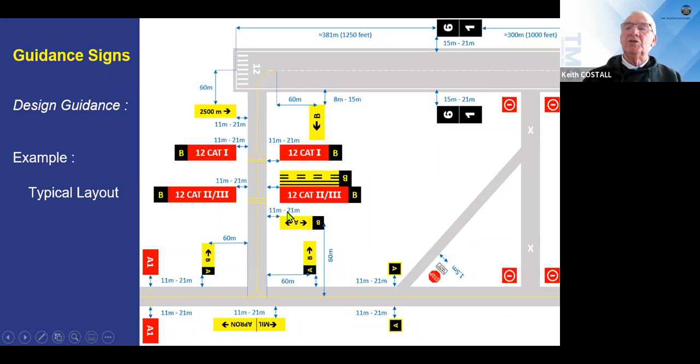There's also the difference here. We show the difference between military and civil, because the basic difference, I'm not saying this is exclusive, but the basic difference in visual aids between a civil and a military airport is, in a military airport, we would have distance to go markers. How far is it before we fall off the end of the runway? That's basically what it's telling us. So there is the fundamental difference.